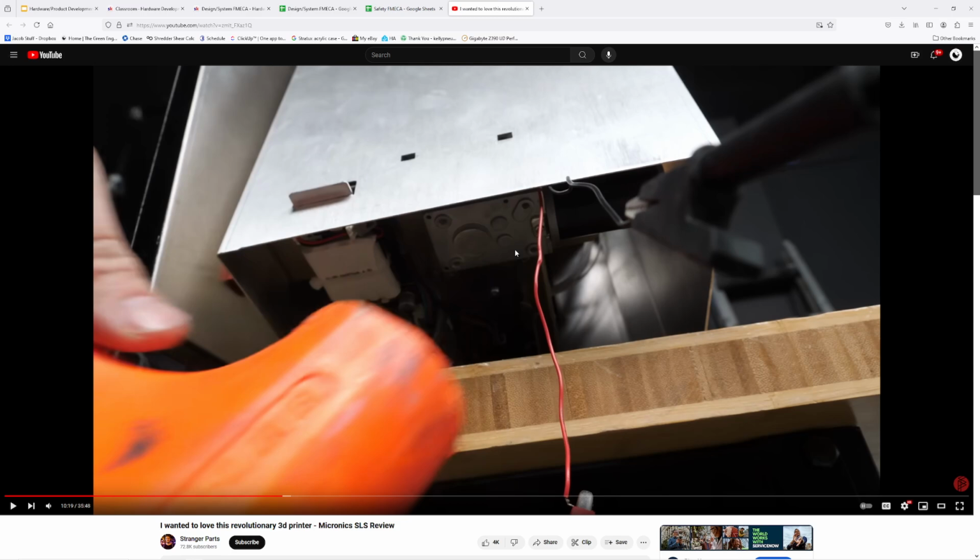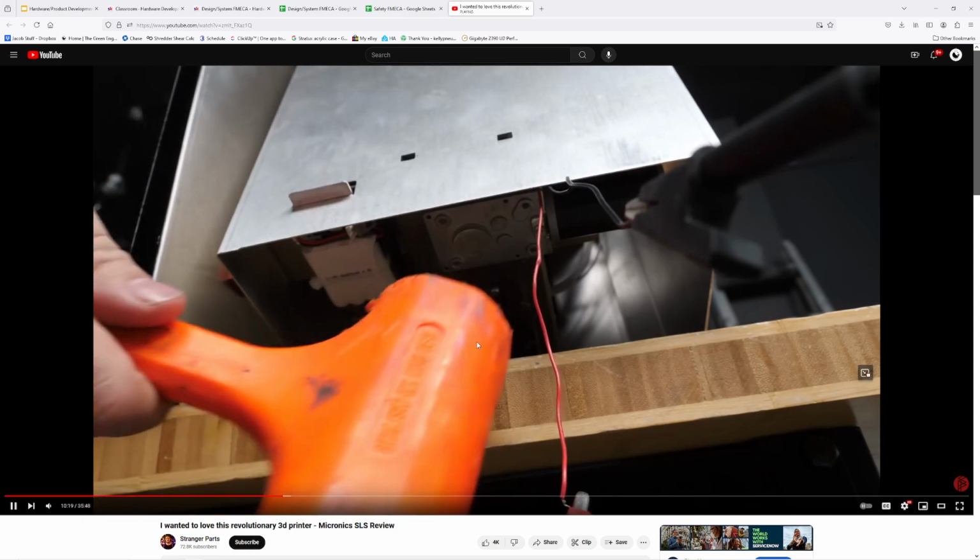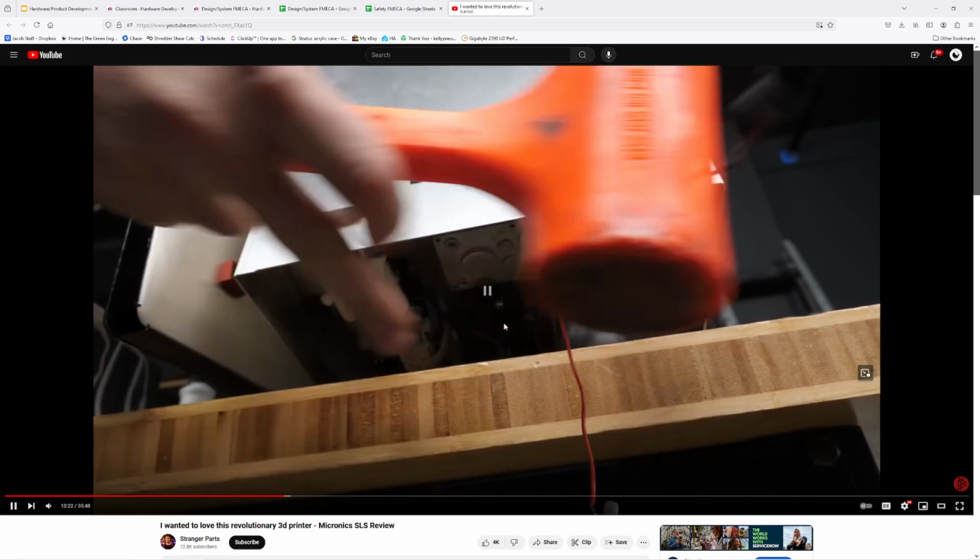If you watch the full video, they talk about how they were planning on adding a way of going forward and then reverse with the auger, but that was never implemented. And we learned later why that probably is. Is that right? Okay. Correct. And here I'm talking to him on the phone, and now he's trying to rearrange the internals to free up this caked stuff. But the unfortunate thing with this powder is if you hit it with a hammer, it's just going to pack further. You keep increasing the packing ratio by jittering it and getting it to tighten up.